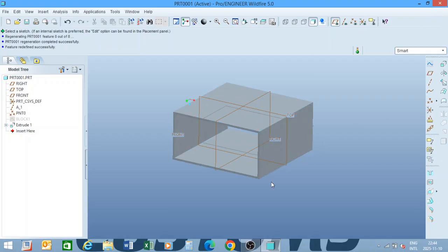would just draw it like this and just extrude it the way I want it and cut it the way I want it, and then from there I can give it to the manufacturing guys and they would cut it accordingly. I don't need to go into heavy detail if it's only for cut sizes and so on. If you are working with a tube laser or an engineering company or anything that requires more details, then yes, you would have to add in the radiuses of the tubing, or the little smaller details of the tube if you are doing a tube for them. But we will work to that in the next videos.